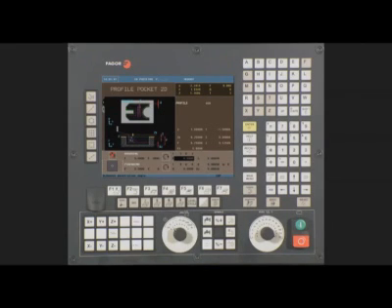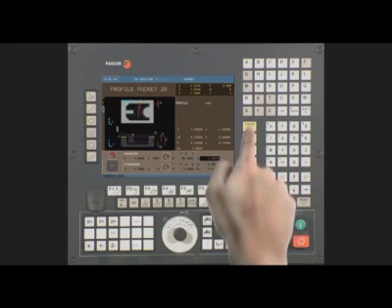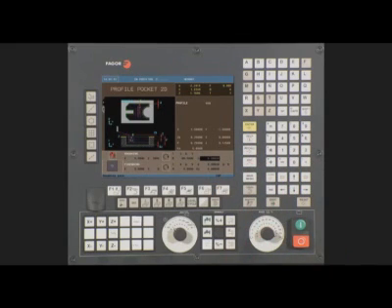This is your sideways penetrating angle. In this example, we are using a center cutting end mill and will be penetrating into the center of our profile pocket at a 90-degree angle. Press Enter to continue. Note, when using a non-center cutting end mill, you will want to select a suitable ramp angle. Example, 5 degrees. This is your step over field. In this example, we'll be using a value of 0.125.